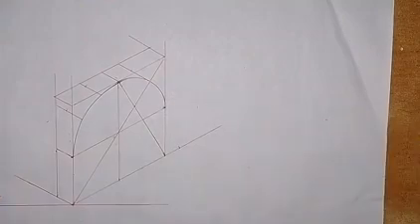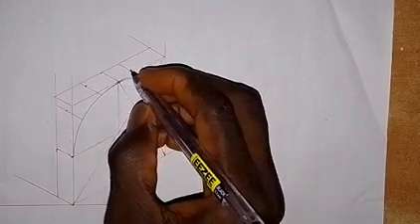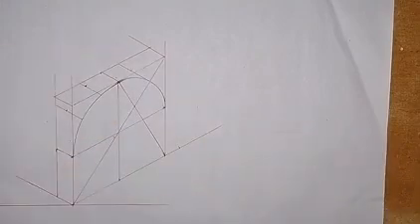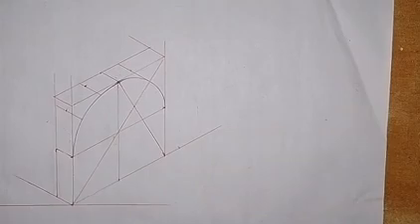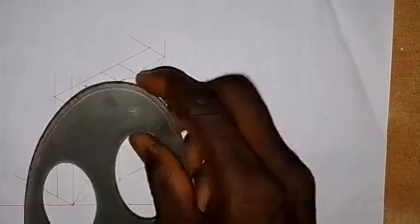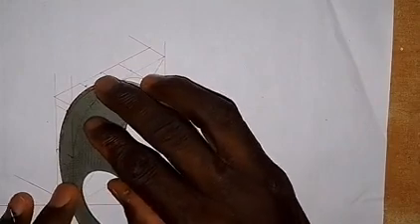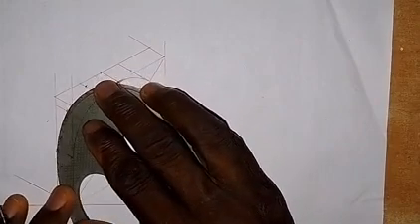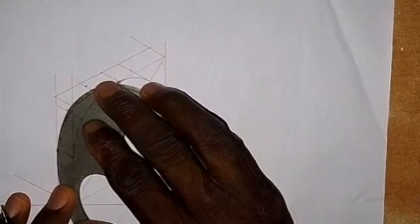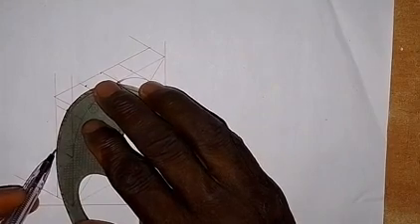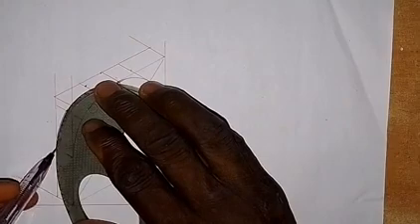Alright, so the next thing that I'm going to do is, this point that we have here, this point, and this point here, going to this point here, we are going to join them together with the use of a French curve, and this is how it goes. We take the French curve, and first of all we connect these 2 points together. You have to set the French curve very well. Make sure you can see the point and draw this line.